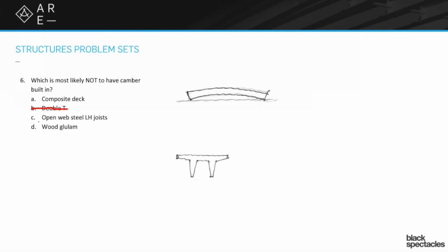And those are absolutely going to have camber, same kind of thing. The camber is going to be built in because that's, for example, Heather's example of putting the roofing on, something like that. Those are fairly light structures, and so in order to give them a little bit more capacity, you put the camber in, and then when it gets that roof load on it, it's going to settle down into essentially the correct slope for the drainage of the roof.